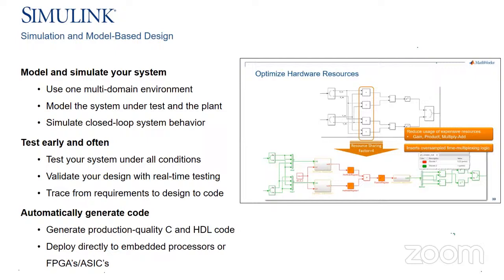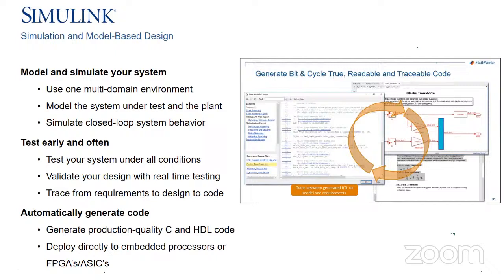So if you want to work with a triangular waveform or the step signal or the ramp signal, you can fetch the block from the sources. Or if you want to display any kind of signal or outcome in the output, at that time you have to use the scope. For other mathematical operations or computations like convolution, addition, subtraction, those kinds of mathematical blocks are available. So these are basically the Simulink, where you can do the simulations or the model based design in this platform.